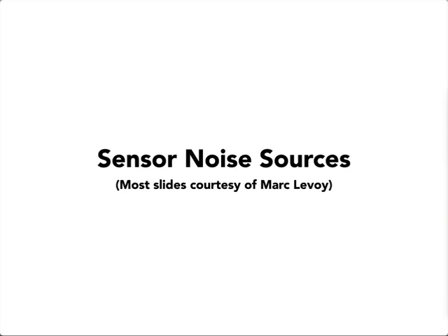Okay, so again, if you only remember one thing about image sensor noise, that would be the thing to remember. That's the fundamental, cannot get away from it source of noise. And as image sensor engineers, we strive to engineer devices that in the situations in which we use them, the noise due to the device is very small compared to the shot noise. Those would be called shot noise limited devices. And once you're shot noise limited, you cannot make a better device for that imaging situation.